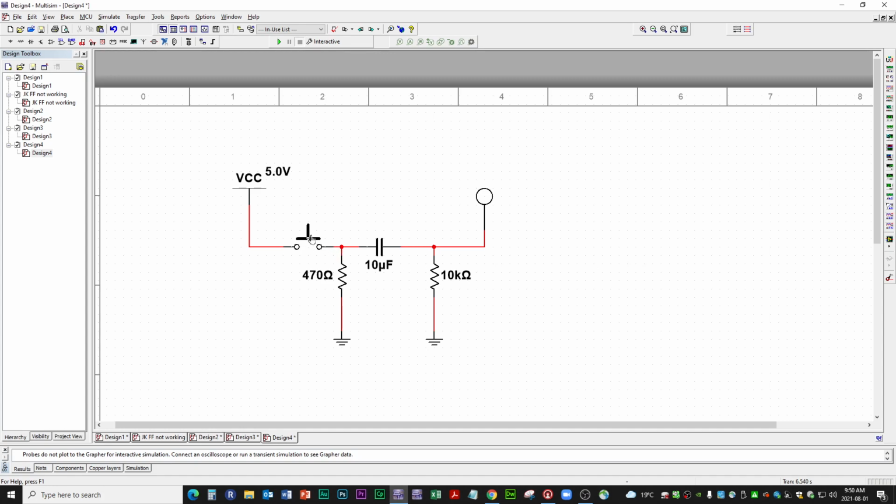If you put your mouse over the push button and click once, it's going to push and spring load right back. So that's the idea of a momentary push button switch. The space bar looks like you can operate it, but it just doesn't work the way we want. Or you can just close it for good if you want. Maybe that's the aim of the Multisim people when they were doing the programming here. All right, start simulating. Press run, which is this one here, and see if we can get the LED to blink. Oh wow, see?